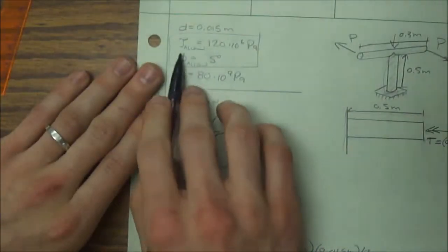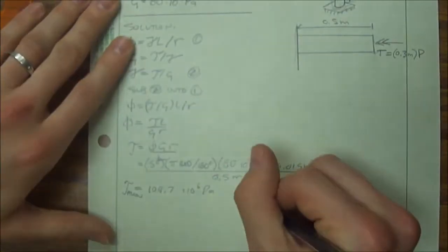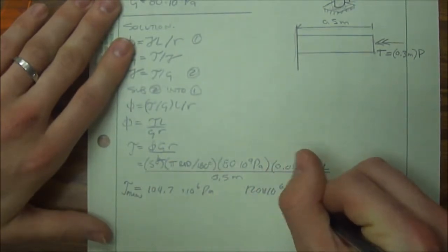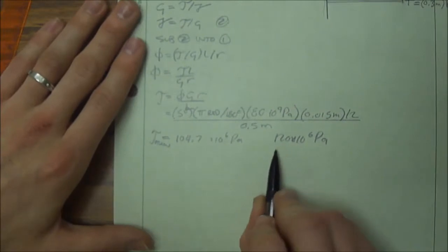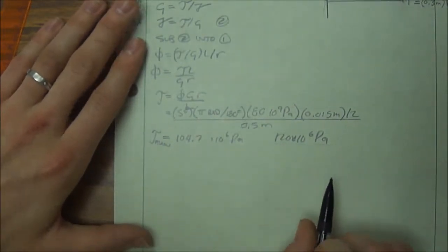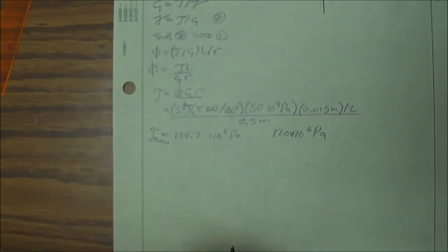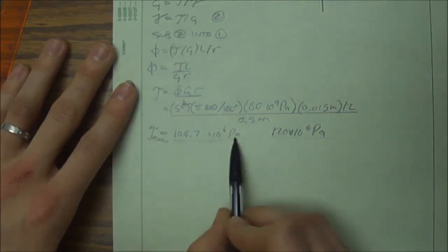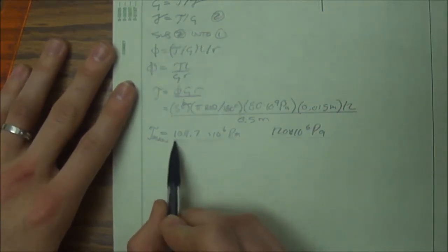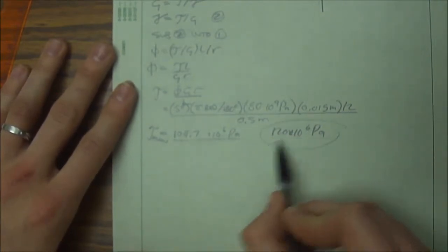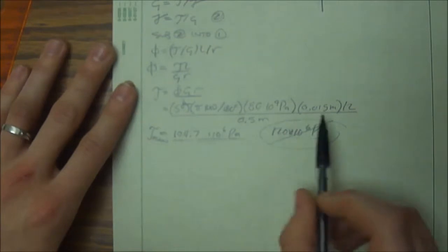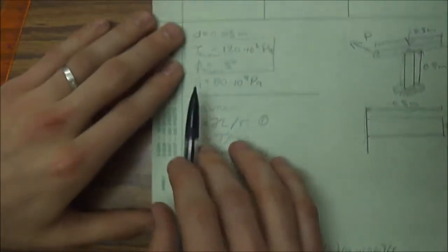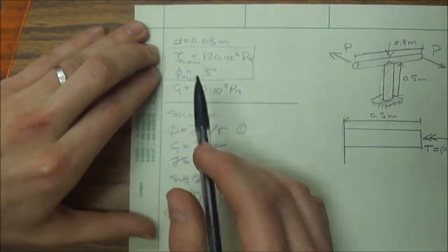Now let me write my other tau allow right next to there, just so that we can compare. So these are my two constraints, and I can't pass either of them. So if I were to start at 0 shear stress and slowly increase, I would break this one first. That's the one that I need to worry about. I'm going to do the rest of my calculations using this, and I don't have to worry about the other anymore, because as long as I'm within these bounds, I'm okay. Another way of saying that is that our allowable angle of twist governs the situation.